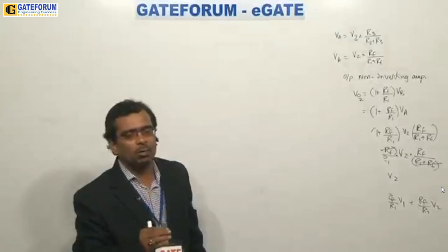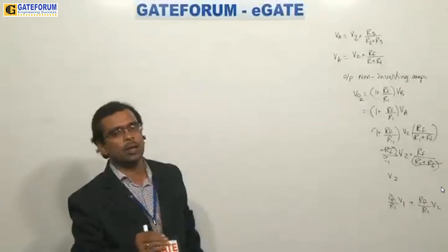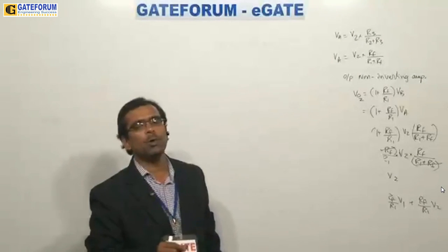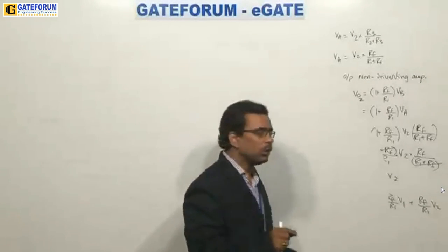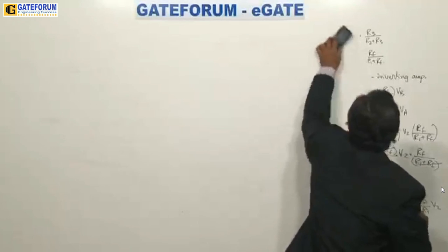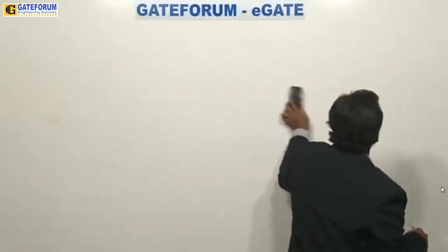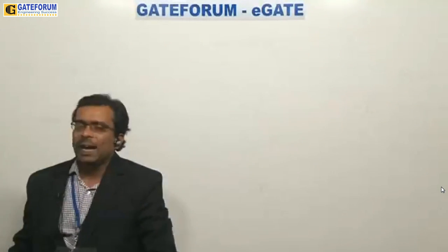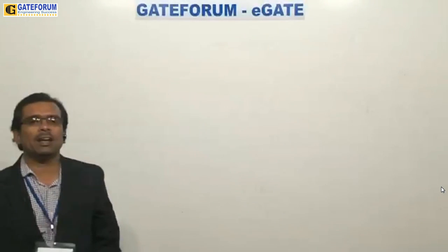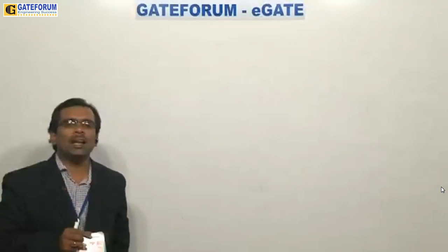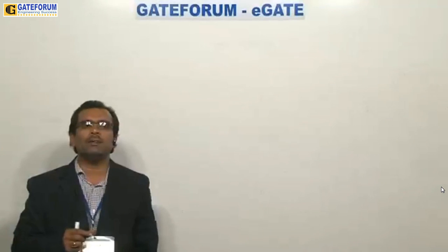But when you get error, what to do? That error job, why you are getting it, that correction is only about offset values. So that is the reason we should study about DC characteristics of this op-amp and AC characteristics of this op-amp. If I give AC characteristics to a BJT, I call it nothing but H parameter analysis. Here also we should study like that, but you don't have any H parameters here. Why? Because you are dealing with the device from outside the op-amp, not inside.